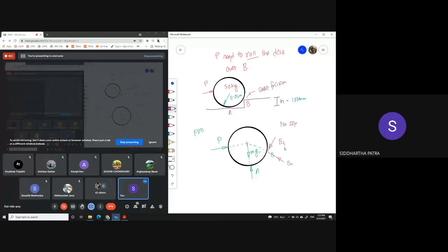There is friction, and it is sufficient. We are not bothering about how much it is, it is indeed within mu s times N. It's just the sufficient amount to not have any slip at B. So the point is, at B there are two reactions, and because these are two reactions, I can show them like a resultant, and I'm carefully choosing a broken line.